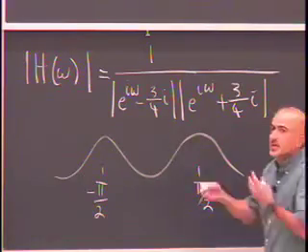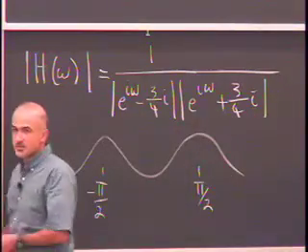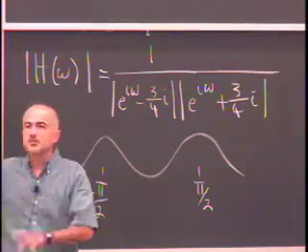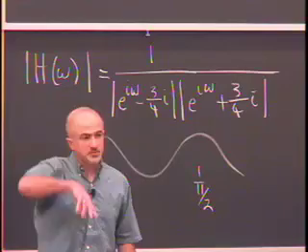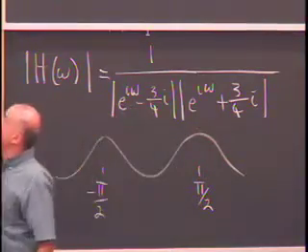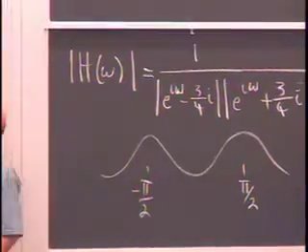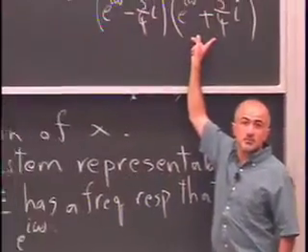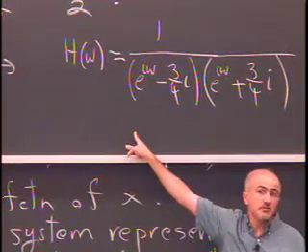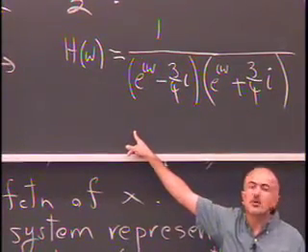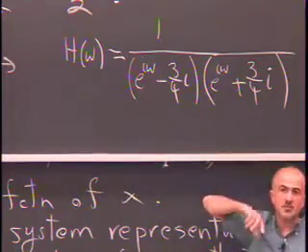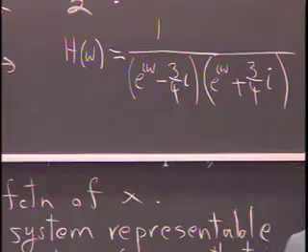We're doing design-oriented analysis. We're studying these filters with design in mind. How do you perturb or change something about the filter to get a different type of filter? And notice, the one thing I forgot: why did I put these in complex conjugate forms? When you multiply it out, you get what kind of a polynomial in e to the i omega? What are all the coefficients? All the coefficients are real. And so when you write out the difference equation, which we'll do after the break, you'll see all the coefficients are real valued. And so you have a real valued filter.